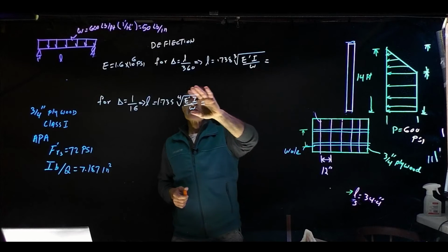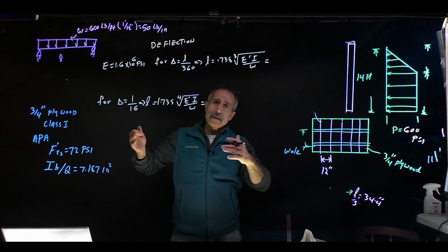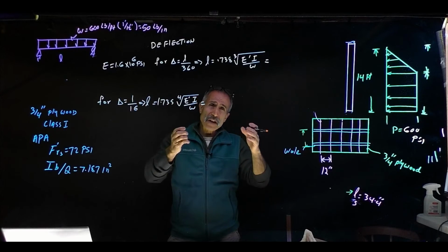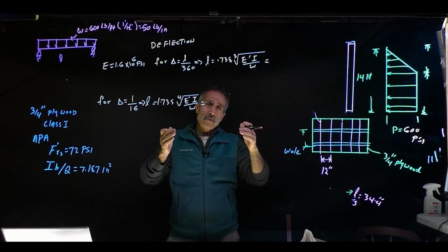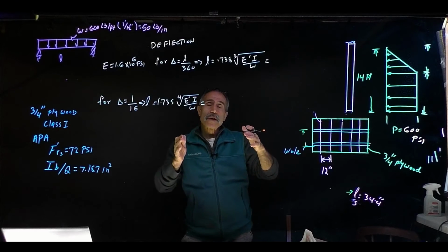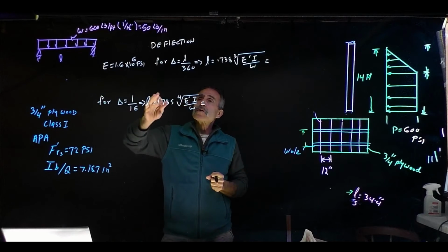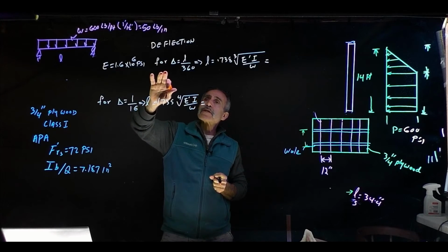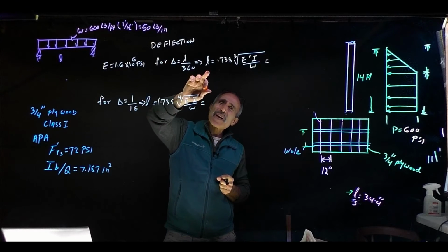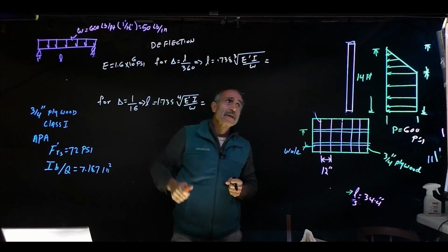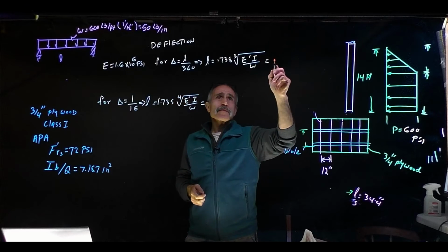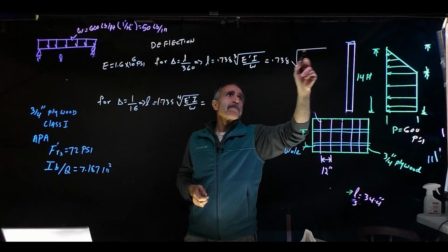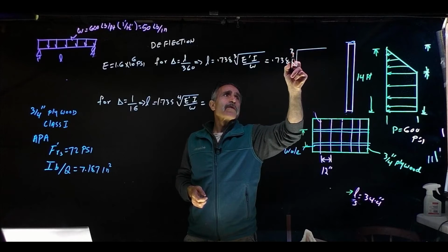Do everything. Like the previous step, for deflection we're going to set two different criteria. We're going to say either L over 360 or a deflection of 1/16, whichever comes out smallest. So we set the deflection L over 360 equal to the deflection equation. That will give us the allowable length, which we did in the previous step. So it's 0.378, basically by power of 1/3.